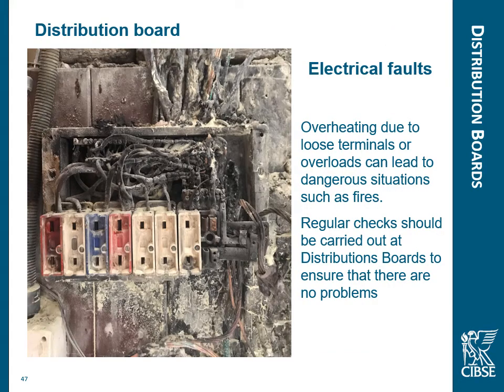Failure to sort out electrical faults, and failure to actually take them seriously, which hopefully most of you do, can lead to fires and loose terminals. It's generally loose terminals that cause fires in situations like this. If the terminal in the board is loose, there's more resistance there. The more resistance, the more heat build up, and potentially it could result in a fire, which obviously none of us would want.